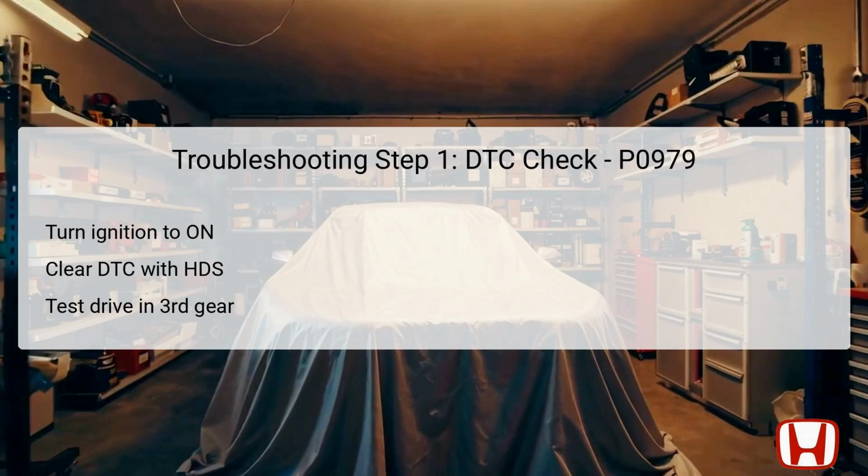The first troubleshooting step involves problem verification by performing a diagnostic trouble code (DTC) check using the Honda Diagnostic System (HDS). Begin by turning the vehicle's ignition switch to the on position, which activates the vehicle's electrical systems. Next, clear any existing DTCs stored in the vehicle's computer by using the HDS tool. This reset allows for fresh readings during subsequent testing.